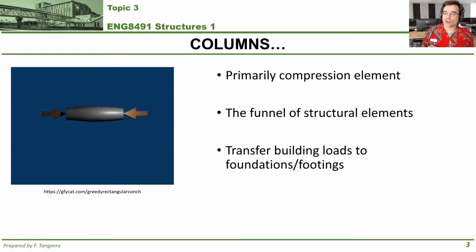And that column above in turn is supporting the floor or roof attached to it, but it's also supporting the column above it, and so on and so forth. So the further down a structure you are, the more that column is supporting, because not only is it supporting the floor attached to it, it's supporting the weight of all the columns and floors above it that are funneling down their way to that column.